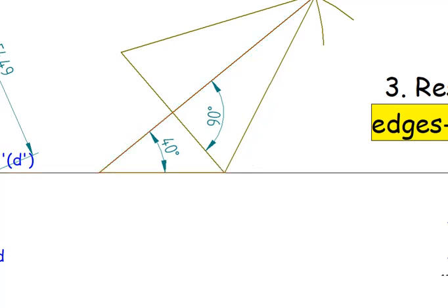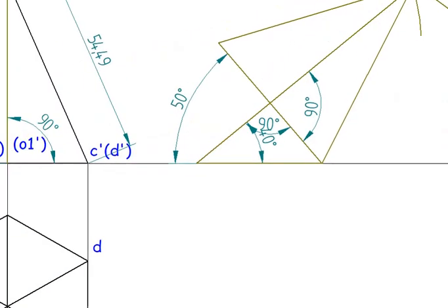This is the triangle. The sum of all the three adjacent sides is going to be 180. So this is 40 degrees. That means this to this I need to maintain 90 degrees. So that means this base should be tilted at an angle of 50 degrees. So that is the reason initially I am going to draw this base which is going to be inclined at 50 degrees and equal to